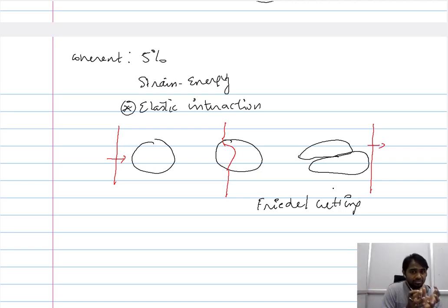So by interaction with the interface, and also by the interaction with the whole of the particle, the propagation is impeded. So we have now seen two ways already how the dislocation can be impeded, how the plastic deformation can be restricted, thereby enhancing the creep resistance. One is by altering the property of the material. So in the two-phase condition, the property of the whole material is adjusted. So by changing the property alone, you can enhance the creep behavior. Secondly, when we impede the migration of the dislocation, the rate at which the dislocation moves, you can enhance the creep resistance of the material.